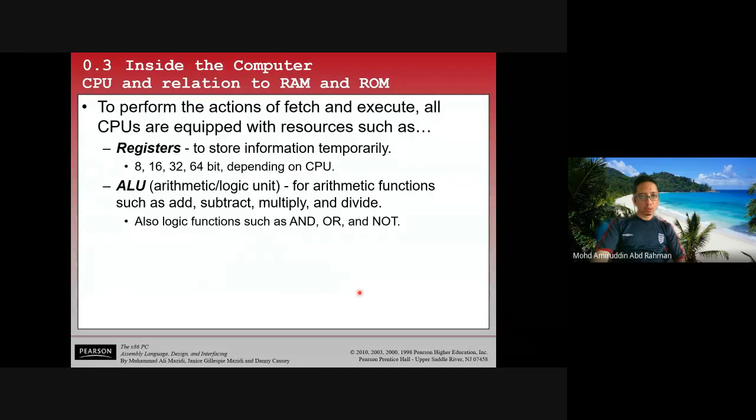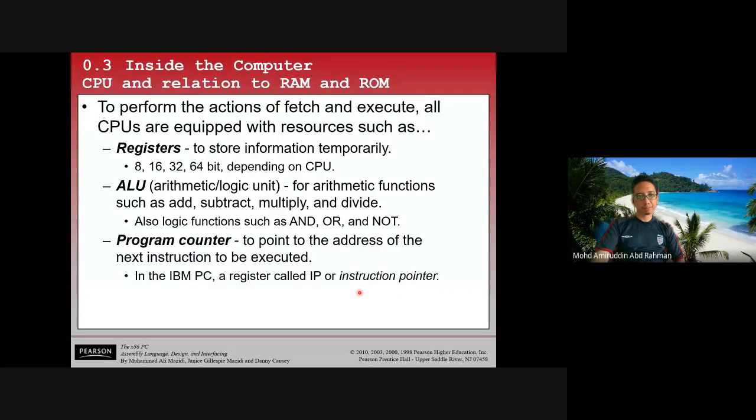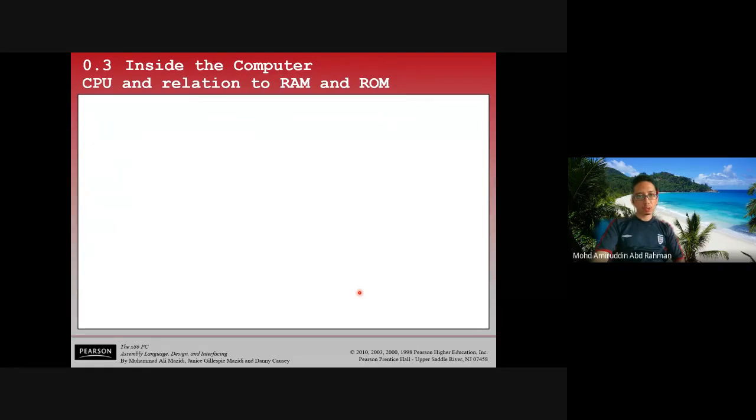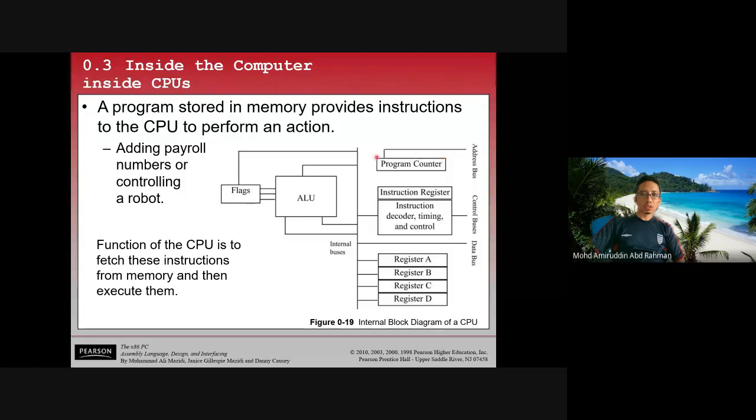Right, so we have functions: add, subtract, multiply, and divide. And also logic functions such as AND or AND NOT. We also have the program counter to point to the address of the next instruction to be executed. So we have the program counter over here. The program counter is connected to the address bus. You remember that this address bus will be connected to the devices.